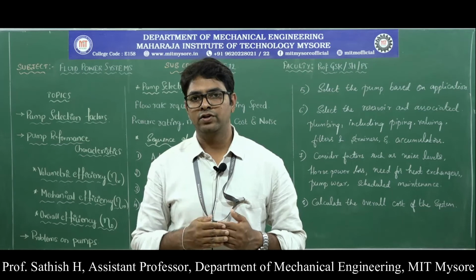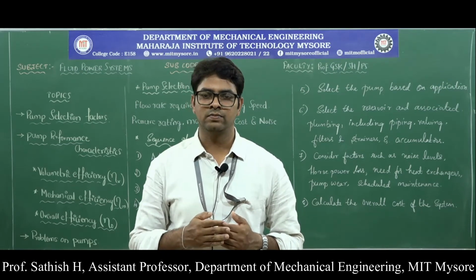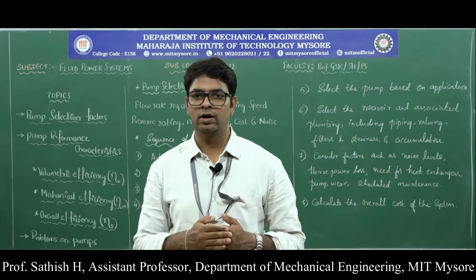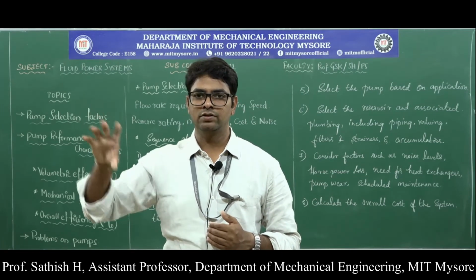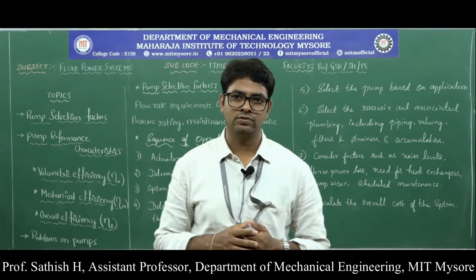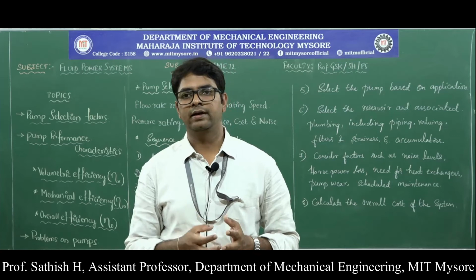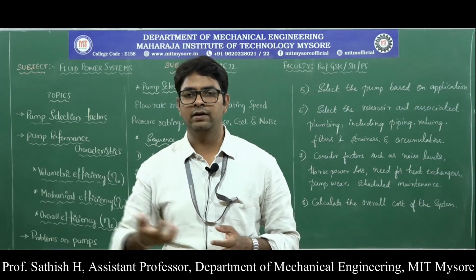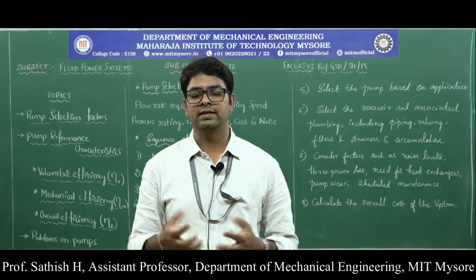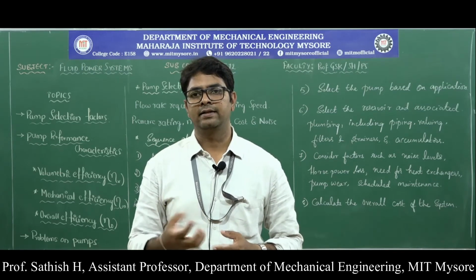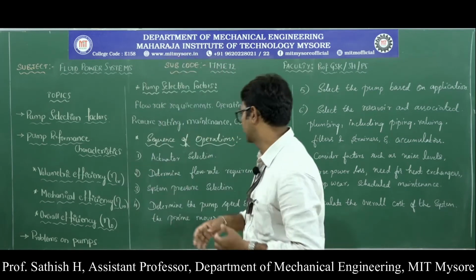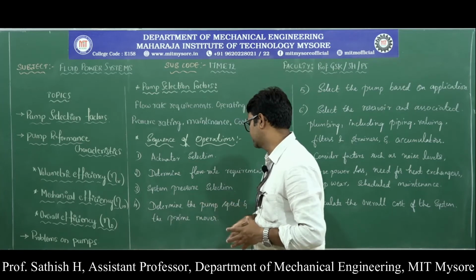So our working pressure, or the pressure of the hydraulic fluid, should be such that it overcomes that resistance from the loads on the hydraulic system or fluid power system. Also it has to overcome the pressure drop coming from the flow of the fluid inside the pipelines. Considering these factors, the selection of the system pressure is very important.